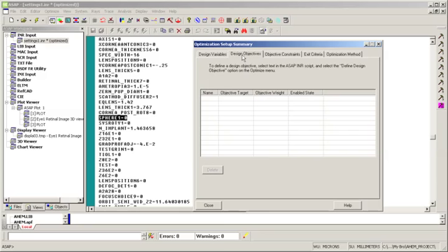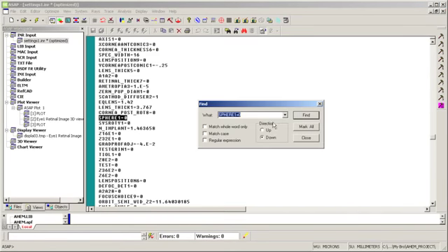So there are various metrics that ASAP generates automatically, and full width half maximum and 50% encircled energy are two good design objective metrics. So I want a compact point spread function, and those two metrics describe the compactness of a point spread function. So I'm going to search for those metrics, or for one of them at least.